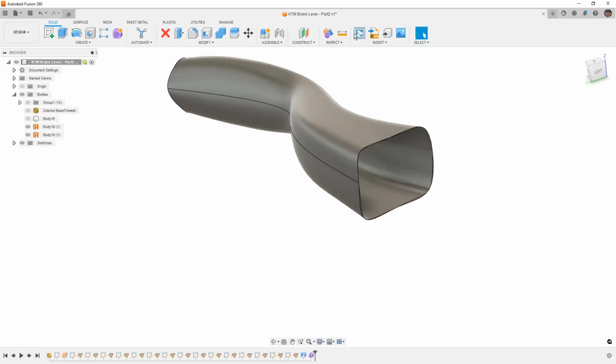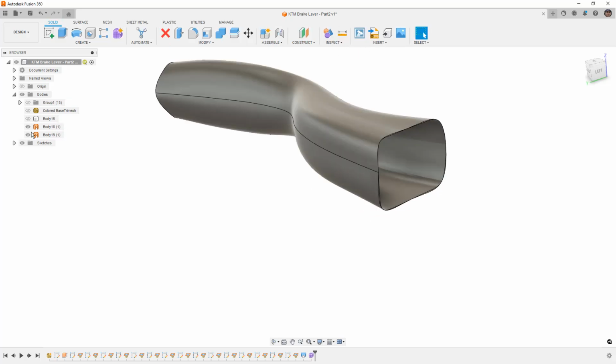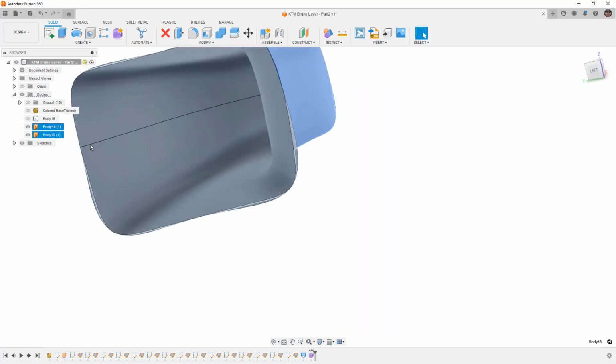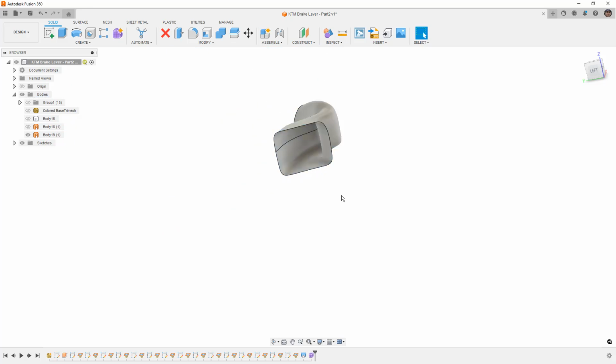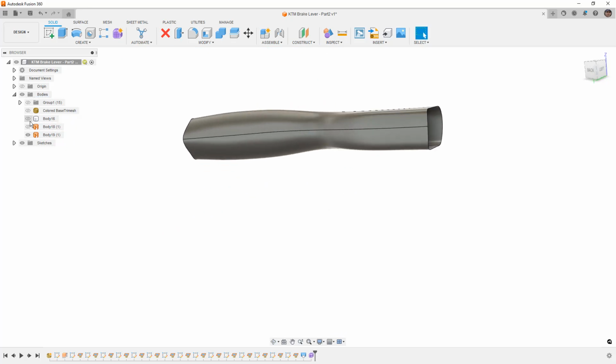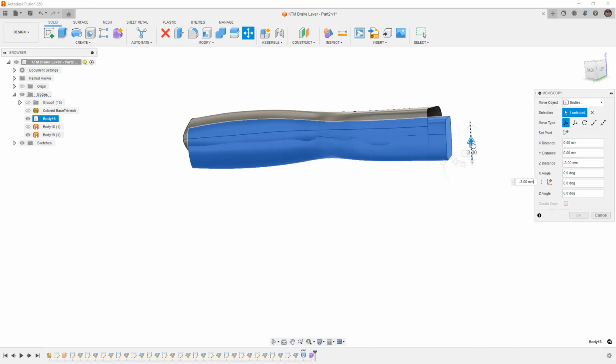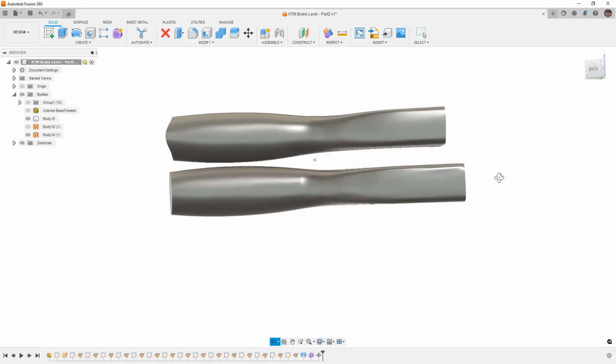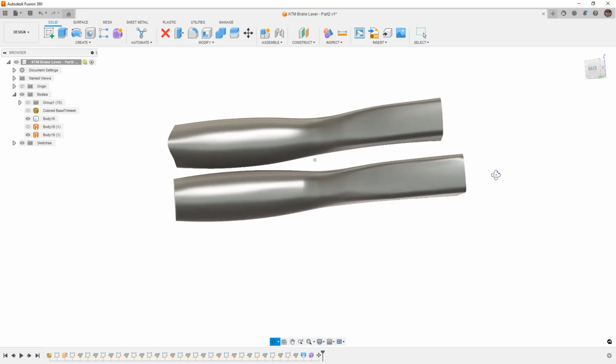When we finish this, what we're left with are surfaces. This first surface was the lower res one, and the second surface should be a little bit closer, so you can see there is a small difference between these two edges. But what we really want to look at is that original body. I'm going to use M on the keyboard and move that down, then Control and 4 to hide the edges. What we want to look at is the difference between the two.